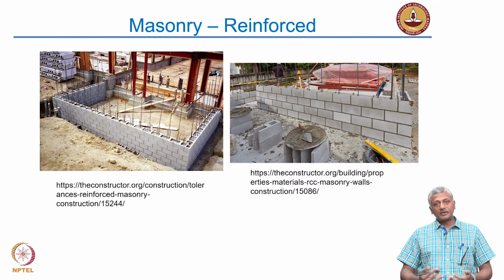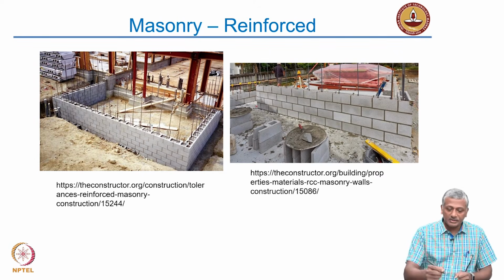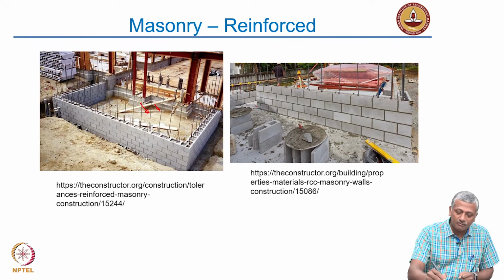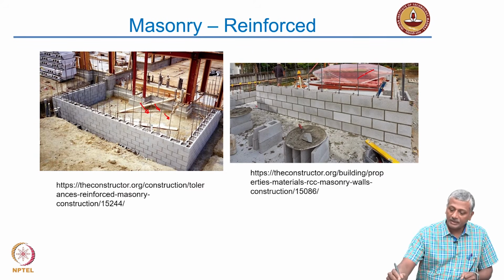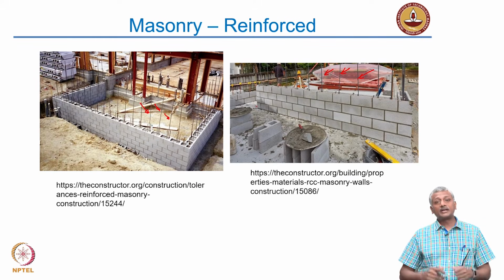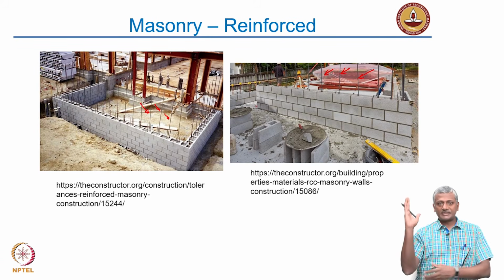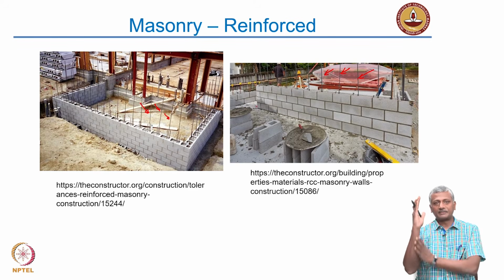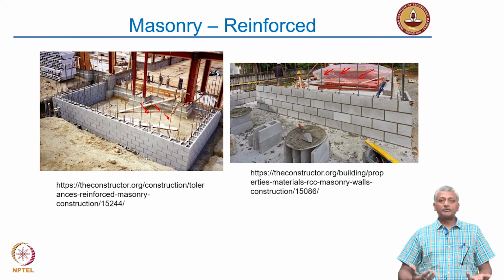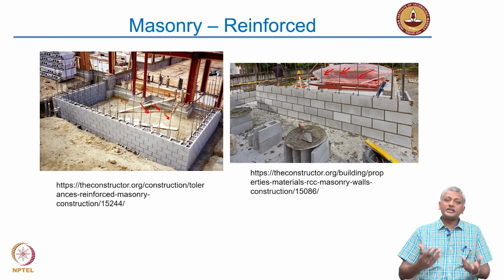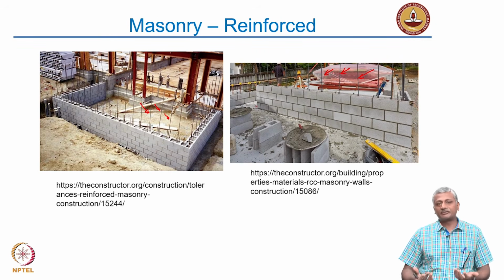Later, people realized you could produce masonry with concrete, and that led to the formation of hollow concrete units. The cavities inside concrete blocks were later reinforced with steel, so that now you could get a composite action out of the masonry wall, not just the compression load that it will take in plane, but also resistance to lateral forces because of the steel. Okay. So, we started utilizing materials and combinations of materials in such a way that they gave the maximum benefit.